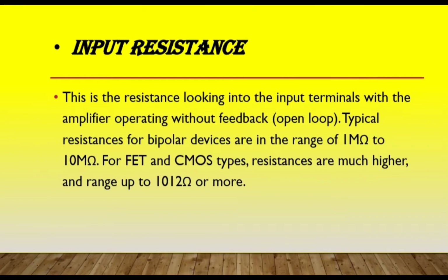So the input resistance of the ideal operational amplifier is infinite. However, the input resistance to a circuit composed of an ideal operational amplifier connected to external components is not infinite. So here's a video of input resistance.